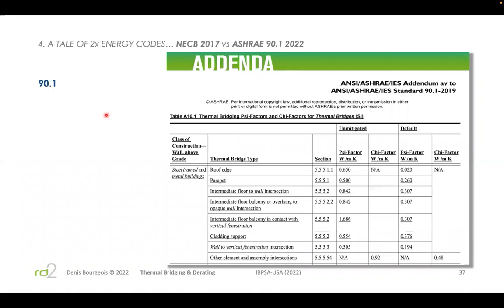and what's required in codes, so ASHRAE 90.1 has two methods which are admissible. One is this modification of clear field values going from a U0 to a UT by modifying the insulation thickness as a final derating step. That's described in 90.1.